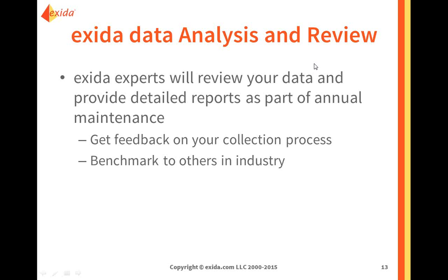But we will also help you evaluate the data, because when we talk about failure rates for safety instrumented systems, what we really are looking at are failure rates for random hardware failures, and we need to distinguish between failure rates for random hardware failures of equipment and systematic failures. We also need to look at product-specific failure rates and site-specific failure rates. So in the past, we've done some analysis work, and we saw that for the exact same product, from one site to another, the probability of failure, and the failure rate, could change by a factor of 2, just because there's a different maintenance culture at one site versus the other. So that is an area where this annual review can be quite effective.